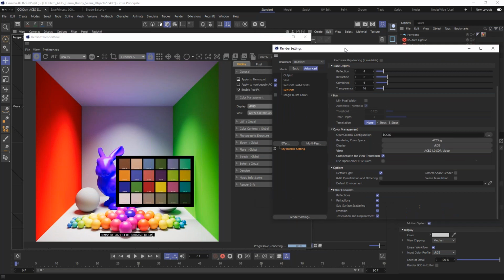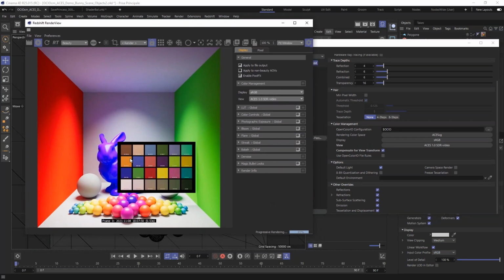Okay, so if we take a look at the scene, we can see that we have some colors. Everything looks great. Something I'm going to do right now is use control, and using control, you can see we have a box displaying the color value. Okay, so that's interesting because we can see two values. Actually 4 values, but I'm looking at the leftmost value, and the ground here looks very white, but is not white. Actually, the left value is the real value before the color transform of ACES, and the second value is the color after the color transform.